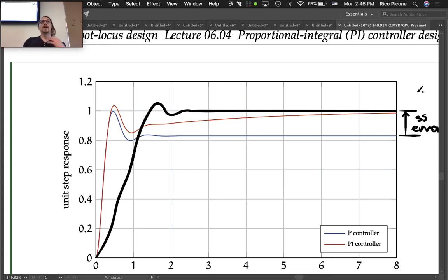So you're going to have to trade off between your steady state error compensation transient and your initial rise transient. And it depends on the design situation. It depends on what you need out of the system, what the performance is. It wasn't really specified in our design problem here which is more important to us, so we didn't worry about it, and we don't really have a way to answer this question. But we just know that there's a trade-off here, and if you're designing the controller, you have to figure out which is better for your design. Does that make sense?